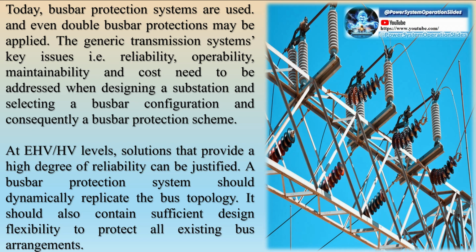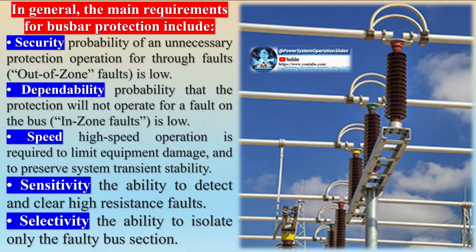There are primarily two types of differential protection relays used for busbar protection. First, low impedance differential protection. This is the most commonly used method. It is sensitive and can adapt to complex schemes, allowing for operation even during substation reconstruction. Secondly, high impedance differential protection. Some system operators still use this method. It is typically less sensitive than the low impedance method but has advantages in terms of simplicity and cost effectiveness.